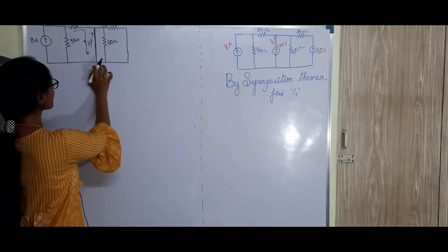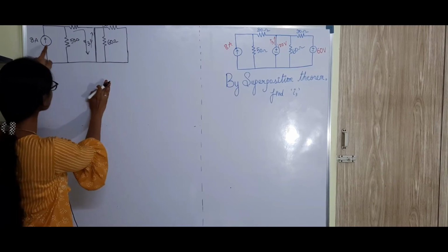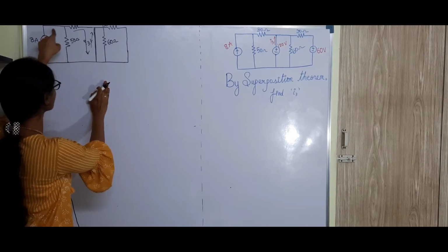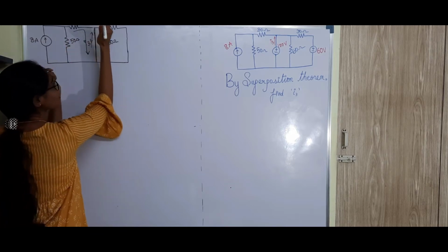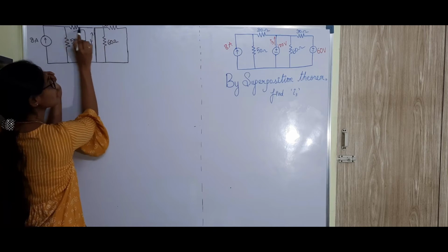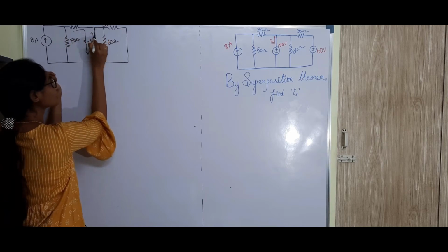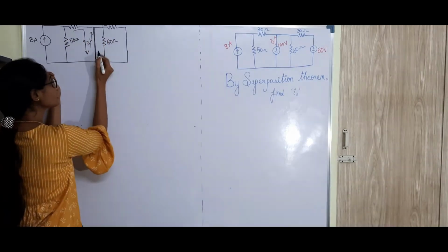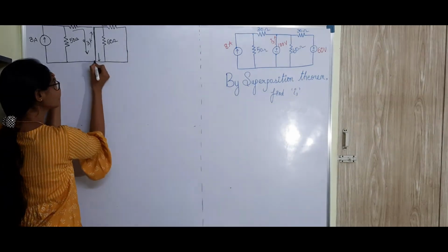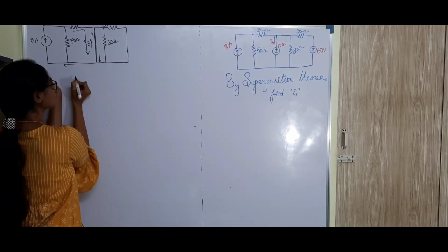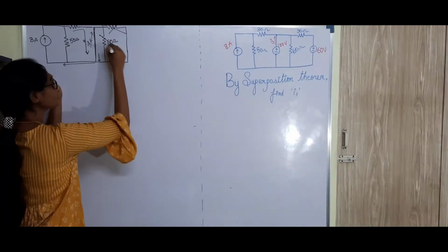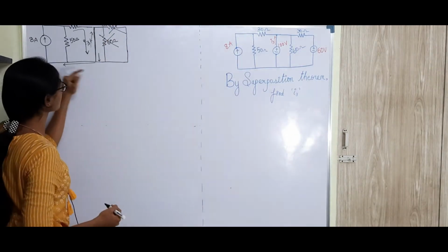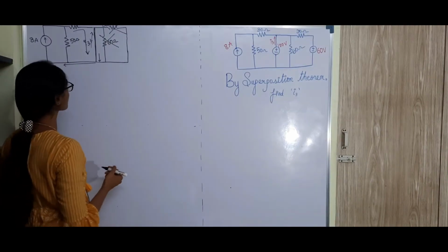Okay, so since we have a short circuit, the 8 ampere will be splitting into the 50 ohm, then into the 30 ohm, and then nothing will go beyond the short circuit. Okay, all the current which is entering the 30 ohm, since this path has least resistance, this current will directly flow into this short and then circulate back to the source. No current will enter through this 30 ohm and through this 60 ohm. Okay, because of this short. So let me find I31.